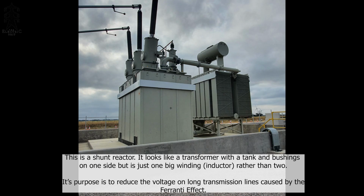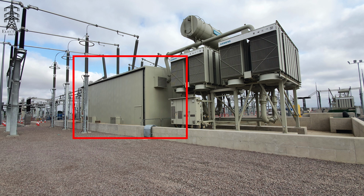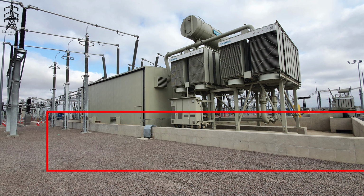That just about covers the components on the transformer. You'll often have a local control cubicle, or LCC, attached to the transformer, or right beside it, and this connects things like the fan controls and the current transformers from inside the transformer to the rest of the substation for power and control. The transformer might have a noise enclosure around it to help reduce the humming sound it makes from bothering its neighbours or the wildlife, and the transformer also sits in a bund, which is a concrete structure designed to contain oil leaks.